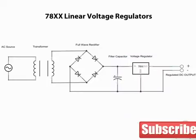This is a typical application for a 7800 positive voltage regulator. We start with an AC source. The step-down transformer drops the AC voltage to an acceptable level for the input of the 7800 regulator. Next, the AC signal passes through a full-wave rectifier bridge and then is immediately filtered by the filter capacitor. This then presents a DC input, yet unregulated signal to the input of the 7800 voltage regulator. The 7800 takes this signal and provides a regulated signal at the output.